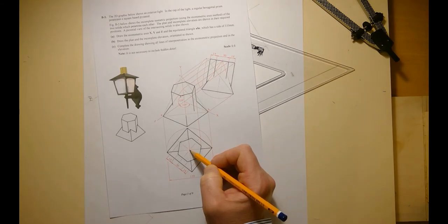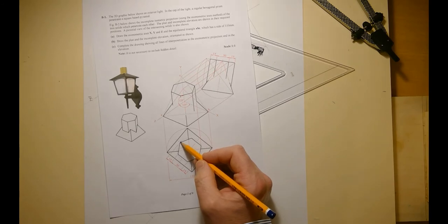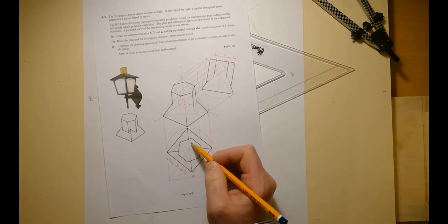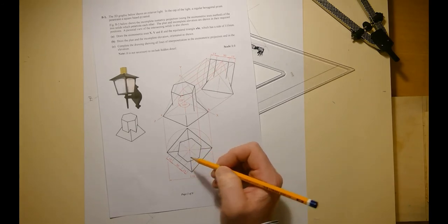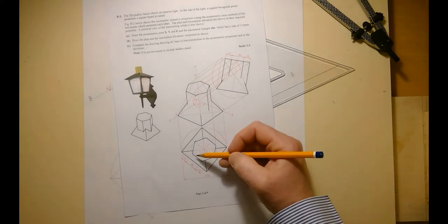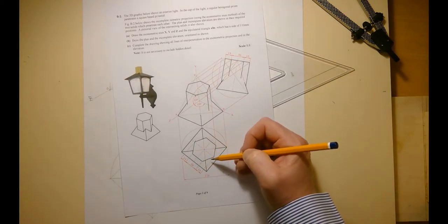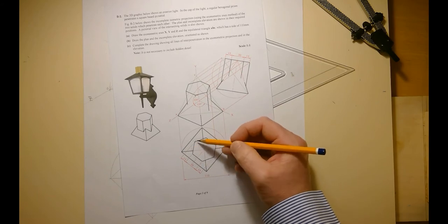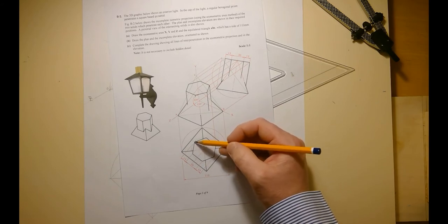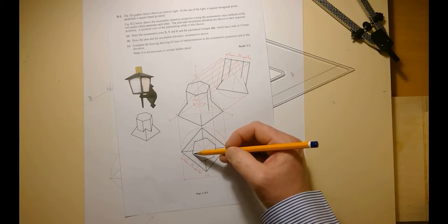After that I can just set my compass to my 30. I'm going to mark off one of my points, and then I'll just be able to tick the rest off then around with my compass. Okay, the length of the side of it is 30, so I can just mark off 30s around the circle that I'm going to put there first, and the radius of the circle is also going to be 30, the same as the side there.